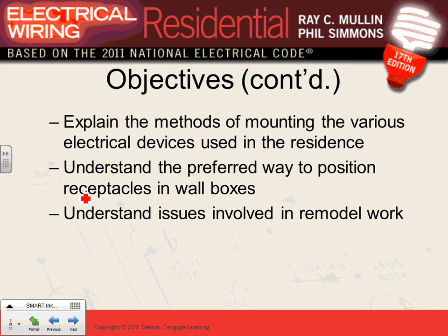So we'll talk about these one by one, guys. There are different ways of mounting electrical devices, different methods of mounting that you can use. In dwelling, we're not going to talk too much about non-dwelling yet. In dwelling, most of it is non-metallic. Wood studs, easy to use, non-metallic. I bet you 90% of what we do in dwelling is non-metallic boxes, and you nail them against the studs. So not a whole lot to it.